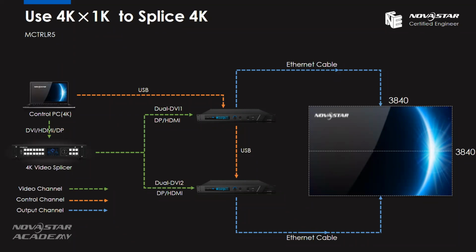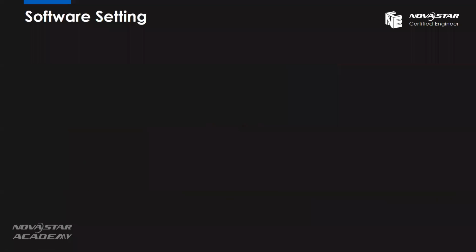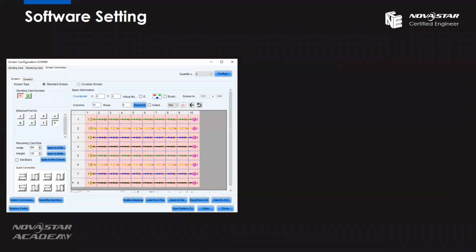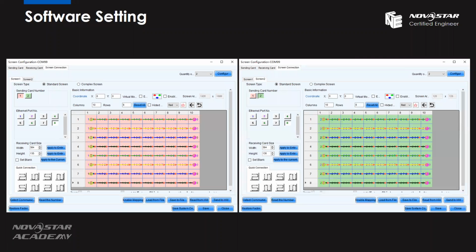And let's see how the software settings work. By the same principle, we go to the screen connection interface, and for the quantity of the screen, we do not need to create 4, we just need to create 2. And with the first M Control R5, we finish the screen connection of the top of the 4K screen. And for the bottom part, we use the second M Control R5, which is screen 2. And for the image coordinates, we still leave them at 0, 0, because the 4K video splicer will help you do the image mosaic.